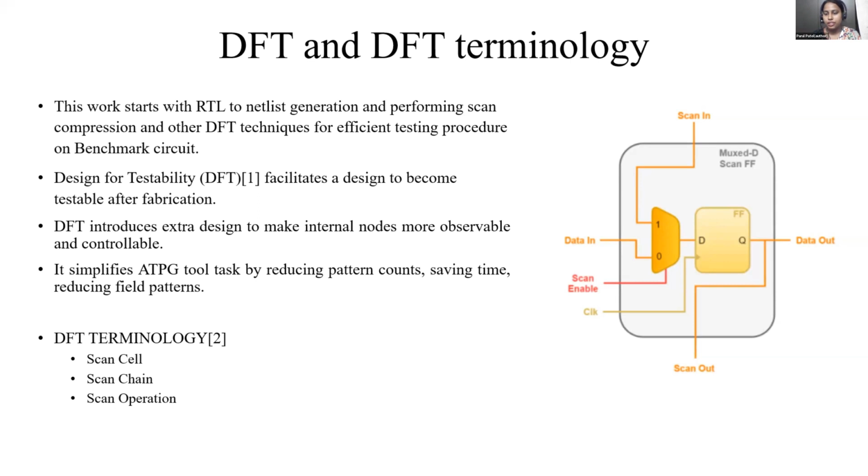This mux will allow us to give two inputs to the flip-flop. One is scan in, another is data in. The data in is for the purpose that the flip-flop will be given its functional input through this pin. If we want to test this circuit, we will input via the scan in pin, which you can see above.